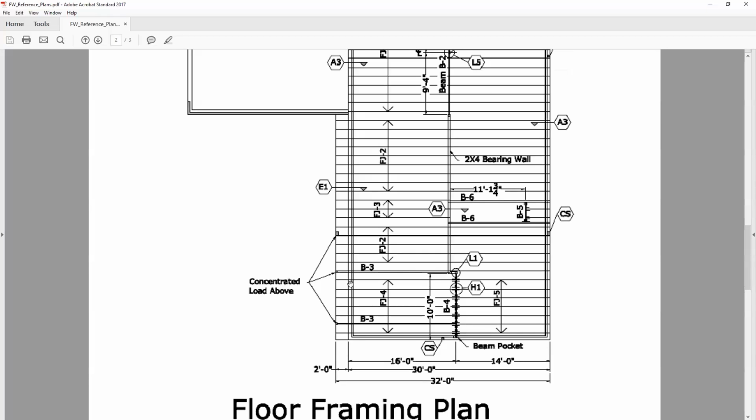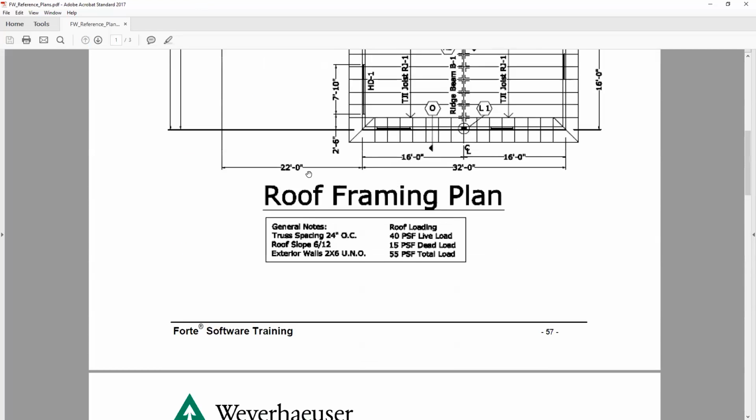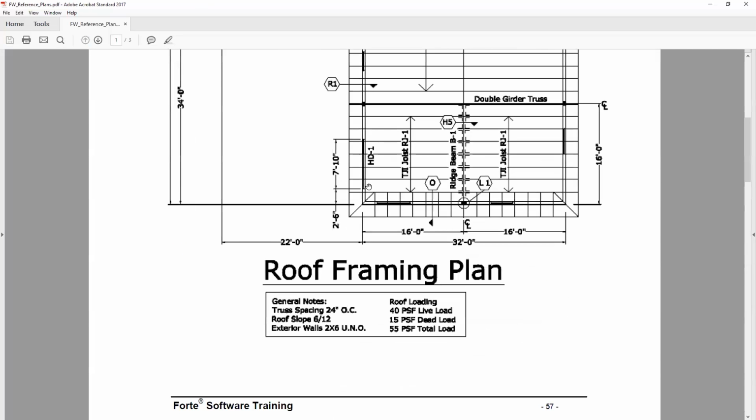And a typical wall is 10 pounds per lineal foot. So we'll put that on there. And then we're also going to have a point load coming down that is acting as the roof trib coming down on it. So 10 foot of roof trib on each side coming down on this. And that all comes off of me looking at this right here.